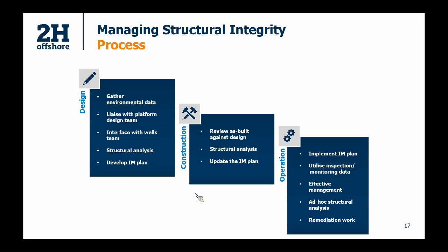You need to be interfacing with the wells team at the design stage. That's to make sure that when you come to do the structural analysis, you're looking at the correct load cases, that you're looking at the actual production parameters you'd expect to occur for most of its life, and also that you're looking at the most onerous injection considerations when it comes to things like strength and stability.